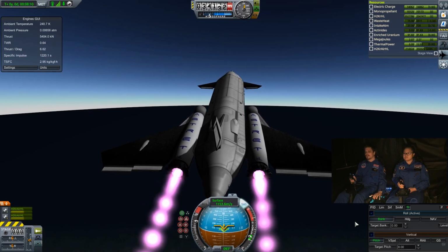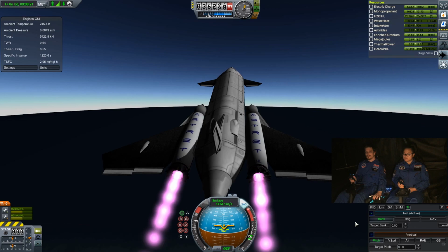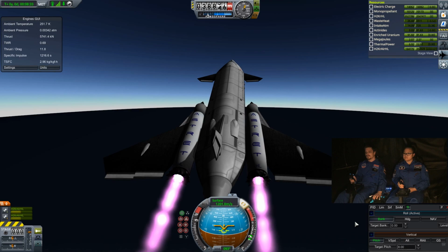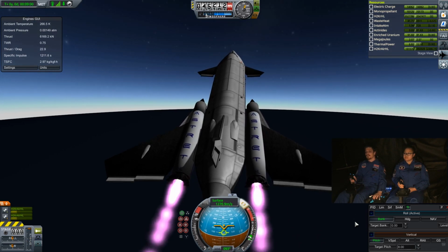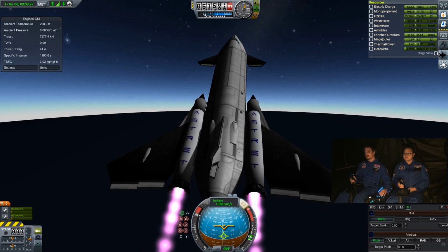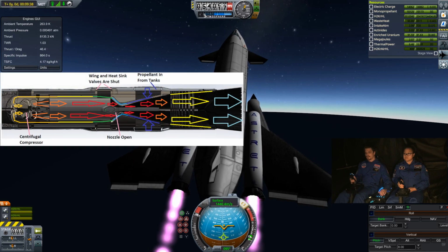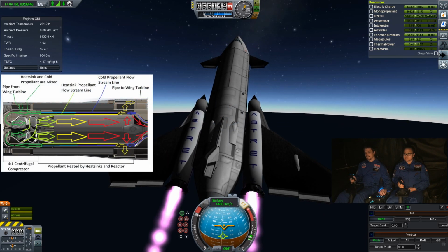Right. Go ahead and switch to 20 degrees. At 40 kilometers, we're going to increase to 6 meganewtons. We're going to go up to 25 degrees. We're going to go ahead and switch to full rocket propellant. Go. Increase to about 35 degrees attitude. Stabilize a little bit.